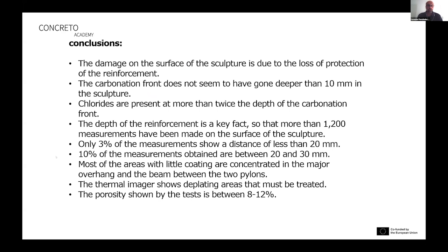these are our conclusions. There is almost no carbonation, because most of the depth of the reinforcement is okay, but we have 3% of less than 20 millimeters in all the surface. But in the case of the horizontal surface, there is a problem because there are a lot more. And also that we didn't have a problem of carbonation, but of chlorides.